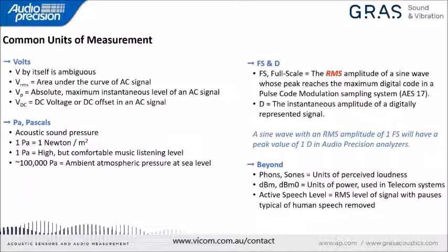If we're looking at a DC signal, it's the only component, but very often we have AC signals or audio signals that are riding on top of a DC value. Humans cannot hear DC. If you will, human hearing is AC coupled, but we worry about DC offset or volts DC in the output of a device because in a speaker, it uses up travel or range in the speaker, and in a power amplifier, it means you will always be dissipating that amount of energy.